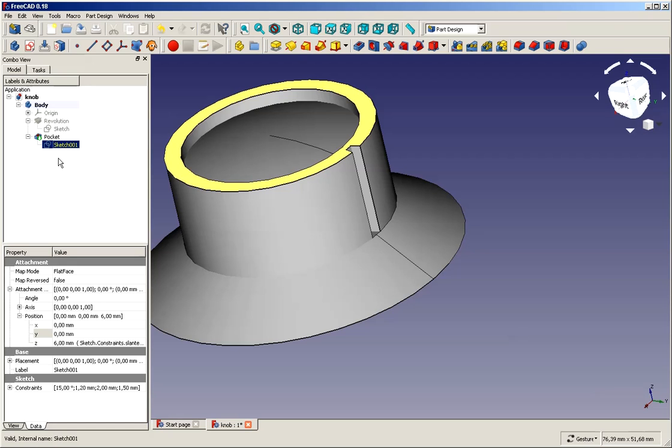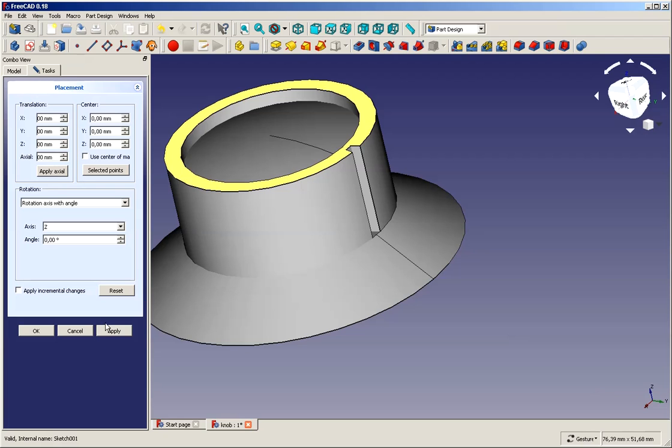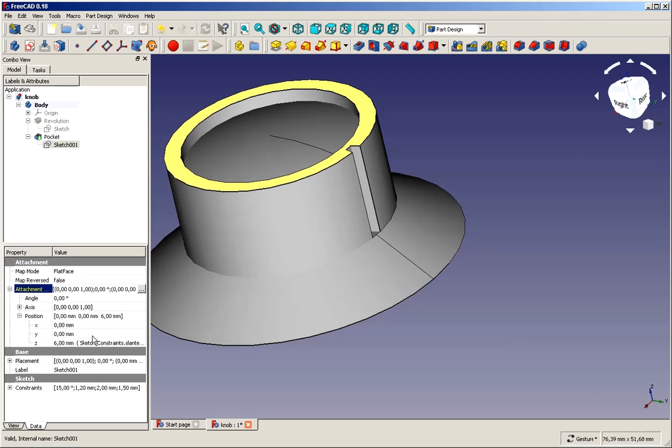Sometimes when you do such movement of sketch offsets or even other offsets like the offsets of a datum plane, and you do this in the dialog here or in this dialog, the problem is that with the version 18 on the screen your sketch is suddenly looking like it is not on the proper plane anymore.